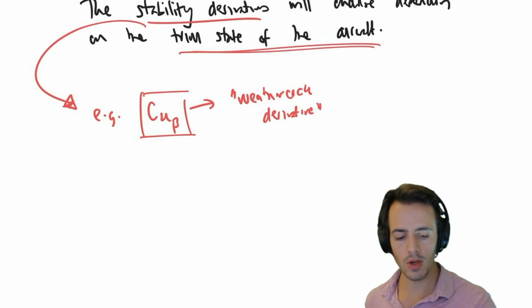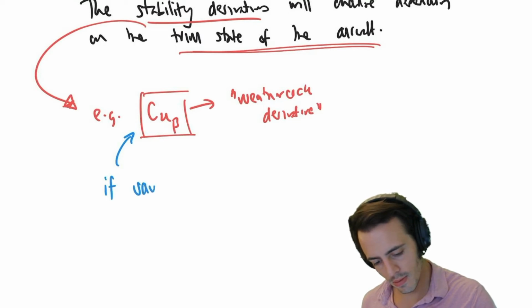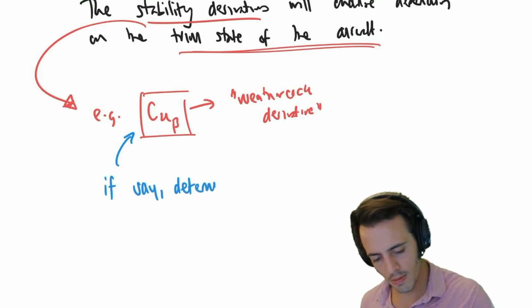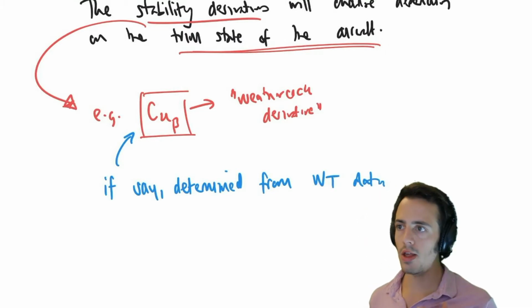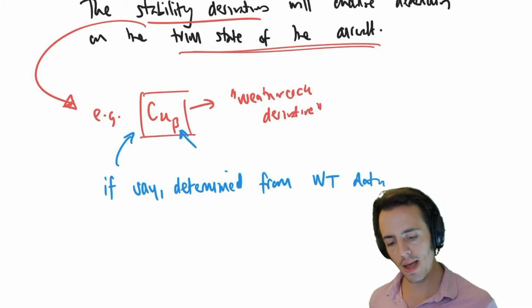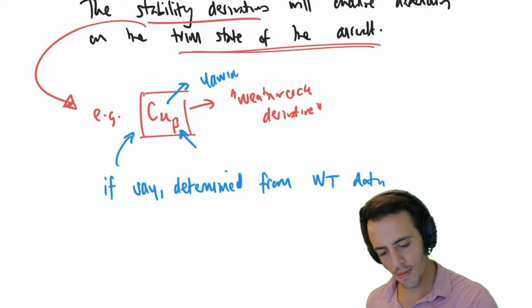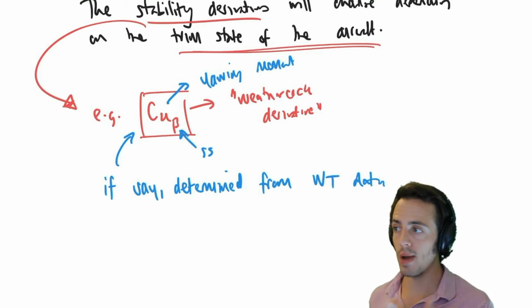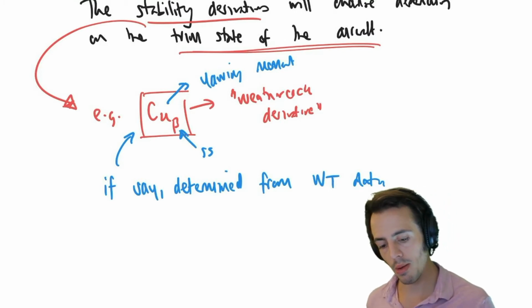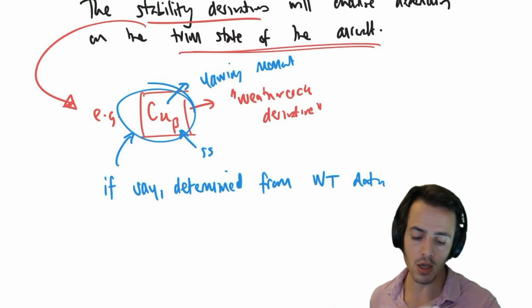So if this was determined from, take for example, wind tunnel data, then this would be performed by putting the aircraft at different sideslip angles and then measuring the yawing moments. And then we determine the derivative based upon those, and then we'd look at the linear relationship and come up with a number that gives us the rate of change of the yawing moment coefficient with the sideslip.